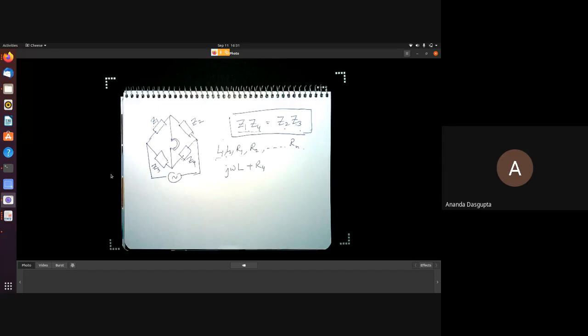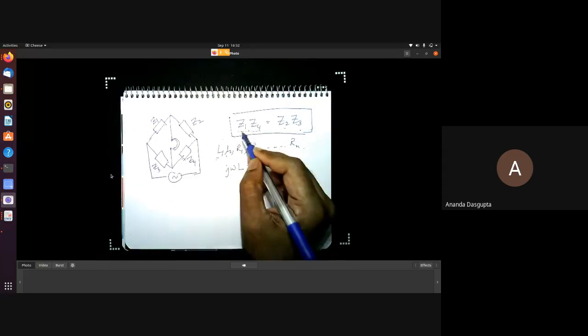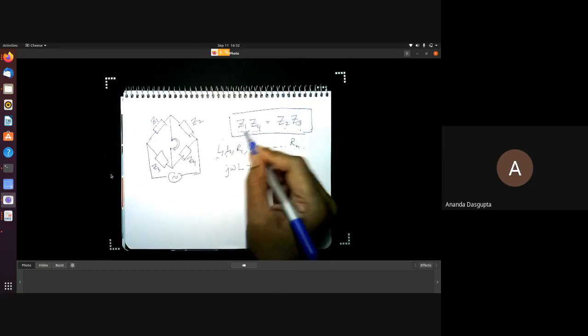So it's not just a matter of a Maxwell's bridge having 2 inductances. It's important which arms you connect the inductances to. That's very much part of the design. So it's not just you throw together 4 arms with 4 components and hope for the best. You have to actually take a conscious decision on what to put where depending on these issues.